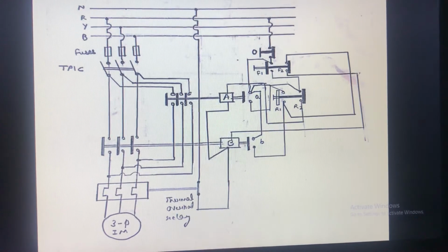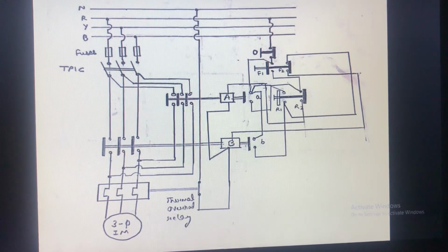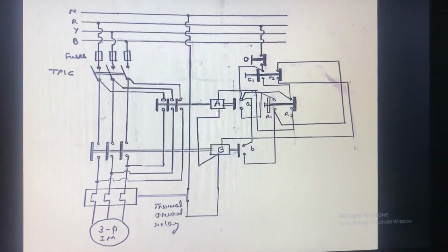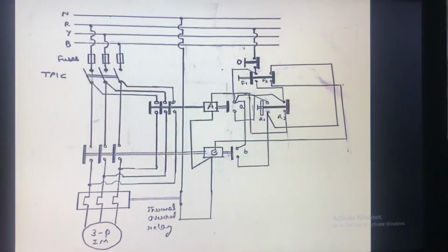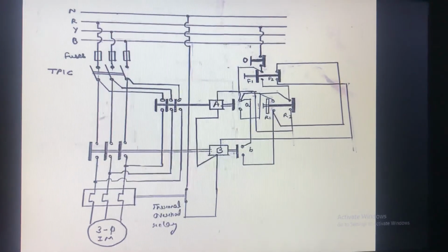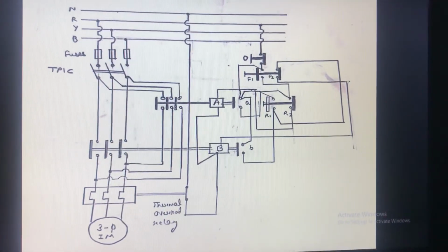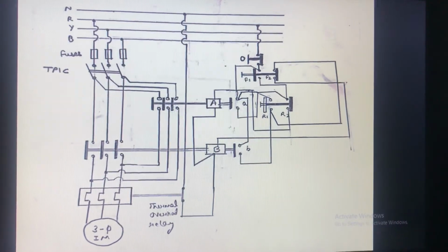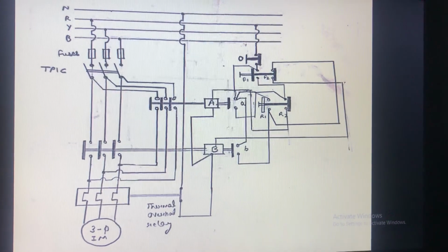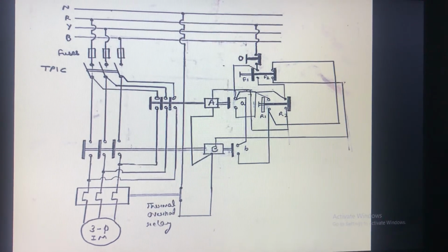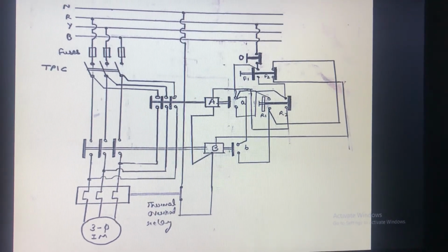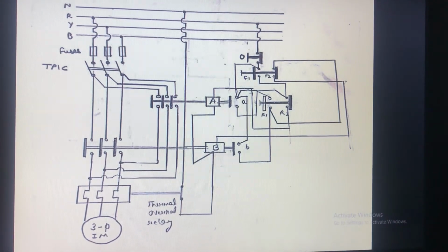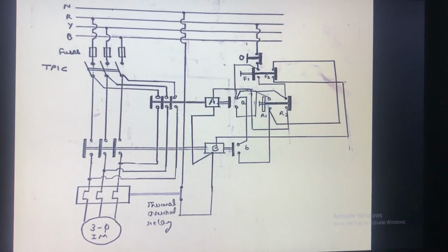Now the motor is getting supply as a phase sequence R, Y and B. In this case, the contactor A is bypassed. In case contactor A is energized, this is for the forward motion. In this case, you can see now the contactor B is bypassed. Now its contact will get open. Now the motor is getting supply from the contacts of A, which were normally open, but after energizing the contactor A, all its contacts will get closed.